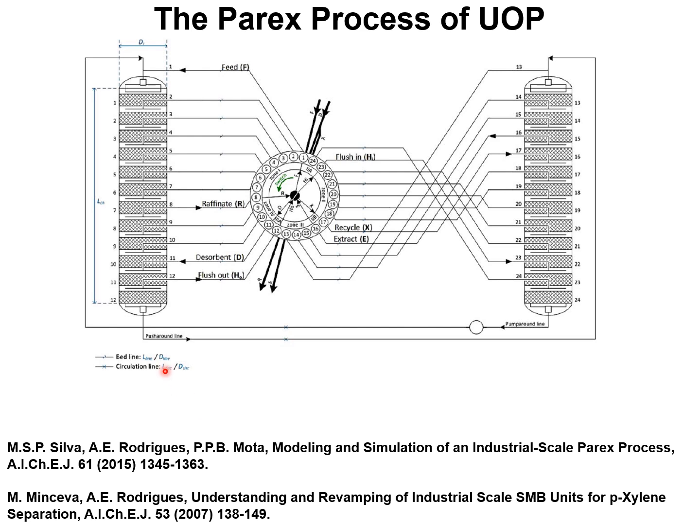The liquid circulates between the 2 adsorbent chambers through the push around and pump around lines. The beds are stationary, and the essence of countercurrent liquid adsorbent contacting is achieved by switching of the valves.